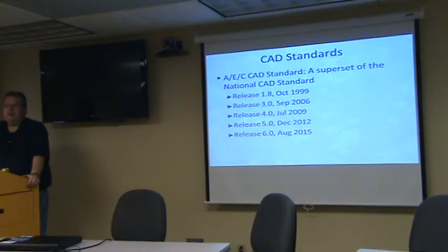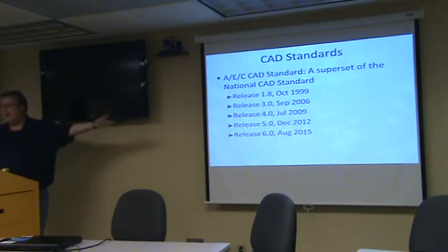It doesn't do a very good job on system families. The Corps separates out their HVAC systems based on what it is, if it's a supply or return. But when you save it out as a file, it all goes to one thing in AutoCAD or MicroStation. So you have to spend your time to fix it because you can't turn in a non-compliant CAD file.